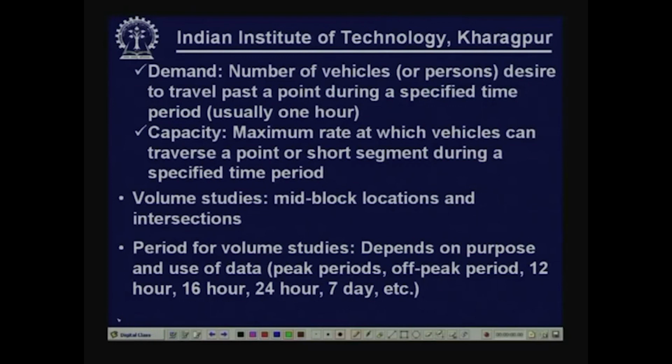Demand. Yes, through traffic volume studies we also measure the demand, not always, but in many cases we measure the demand actually. It is the number of vehicles or persons who desire to travel past a point. Carefully observe this part, desire to travel. Whatever we are actually measuring in the field, we have to be careful whether we are really capturing all those who desire or we are capturing only a part of that. So, the number of vehicles or persons who desire to travel past a point during a specified time period, again usually 1 hour.